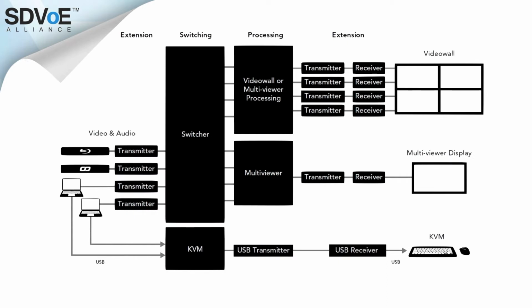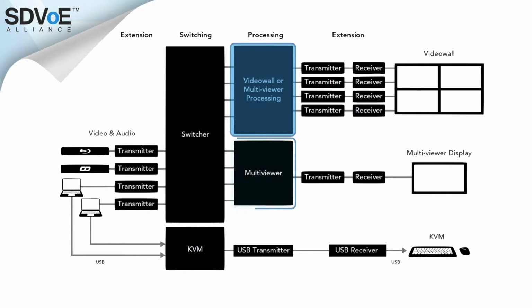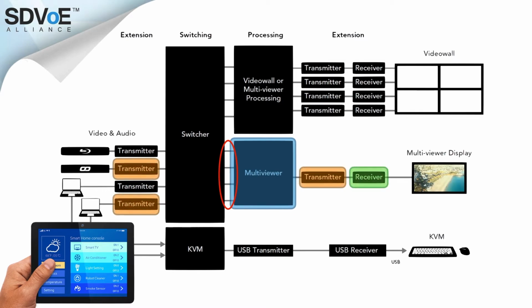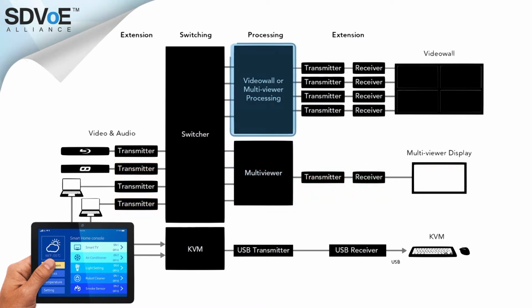Functionality also plays a major part in the cost of a project. If features such as video walls or multi-view applications are required, a traditional matrix switch is unable to help. So, extra equipment has to be added, which further adds to the cost. With more equipment comes more control complexity. It takes a lot of programming and testing to ensure the correct output on the matrix switch is selected prior to the multi-view processor selecting the correct sources to be presented within the display, or to check the video wall processor is pushing the correct image from the matrix to the correct display.